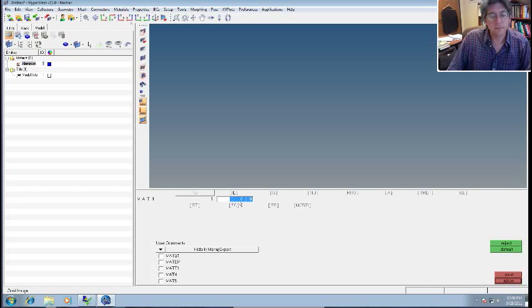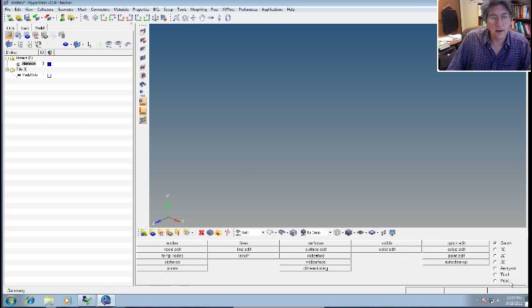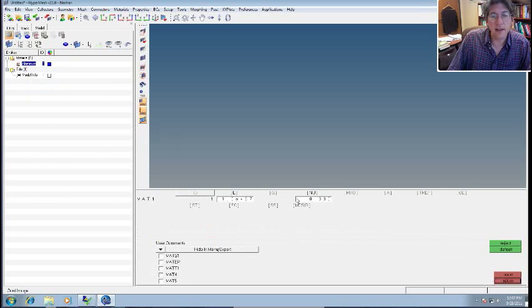So let's make the material. We'll use inches, pounds. So we'll define Young's modulus as 10 to the 6th psi, and we'll put in 0.33 for Poisson's ratio. It's really all I need to do. You can actually see here you can add additional lines for other optional lines in the Mat 1 card. But that's all we need. So you just hit return. And now it's created. Okay. So for example, you can go back later on and edit those if you want to.